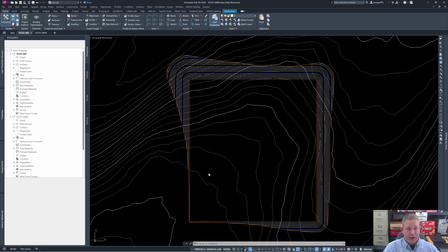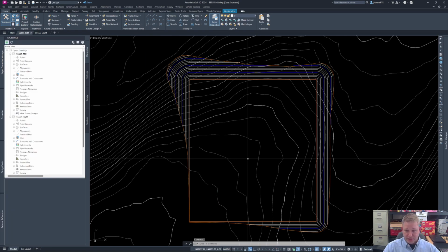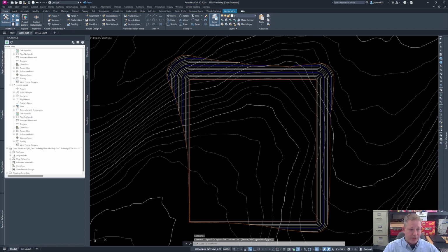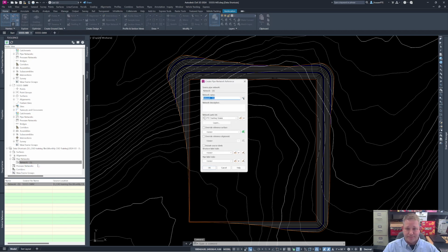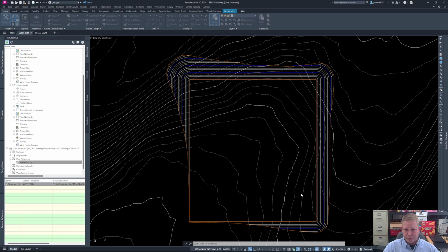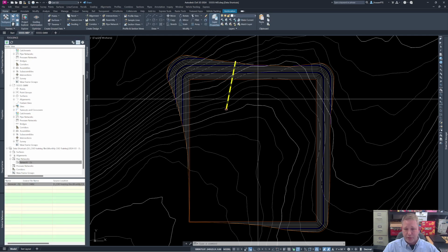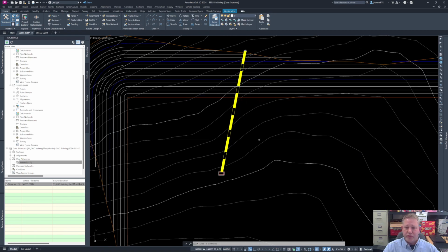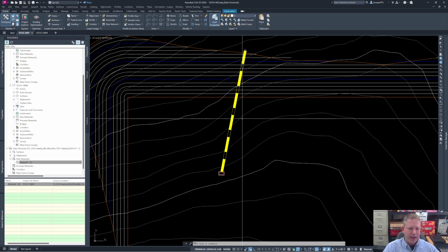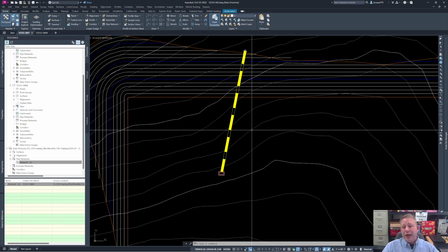So if I go back to the MD drawing that the designer may be working on, we can now go down to here, expand the pipe networks. There's our Network 5, and we create a reference. It goes through. See, we want to change that. And I think we'll leave everything else the same. Now notice when I brought that in, the labels did not come in with it. That is one thing I wish it would be able to do. I haven't found a way to make it do that.